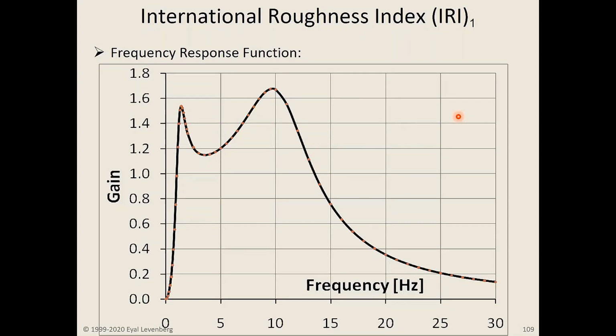Another example is when utilizing the IRI index to represent roughness in city streets. This could also be misleading because the travel speed is much slower than 80 kilometers per hour in cities. So, although the IRI is utilized and reported by engineers across many pavement types, it is most appropriate for highways, for which it was originally conceived and developed.